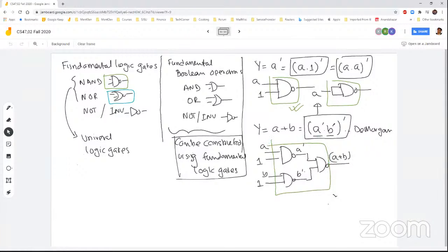So that means if I have a NAND gate and want to use only NAND gates to implement any logic, given an arbitrary logic expression, I should be able to do it because I can express OR with a NAND. Sorry, my mistake. Our target was to make a NOR here, which is not a problem, as it just needs one more inverter at the output.